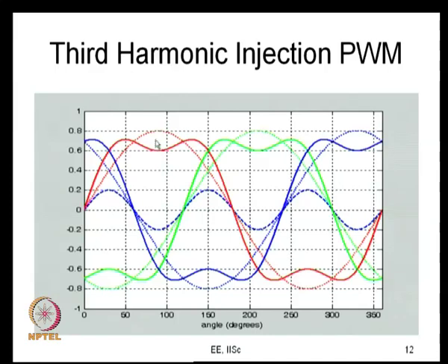So, what happens? The peak value comes down. That is, whenever the R phase sine has a positive peak, the common mode component has a negative peak. So, it brings down the total value now. It is something like its head is bent down a little. You are passing through a door, and the door frame height is not very high. So, you just gently bend your head and you get into that. This happens in many old buildings in India. So, like that the head is slightly bent here, and so you can do this now. So, what you can do effectively is, you can see the peak value of the MR star has come down, as I pointed out earlier.